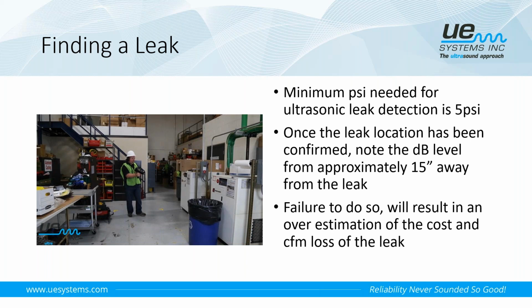We talked about the decibel level, but also what's needed is the pressure and then the cost per kilowatt hour of electricity. Those are the three factors that we need in order to be able to quantify, or put a dollar amount and a CFM loss to, that leak. One thing that's important to note is, where do we want to take that decibel level reading, or at what distance away from that leak do we want to take the decibel level reading?